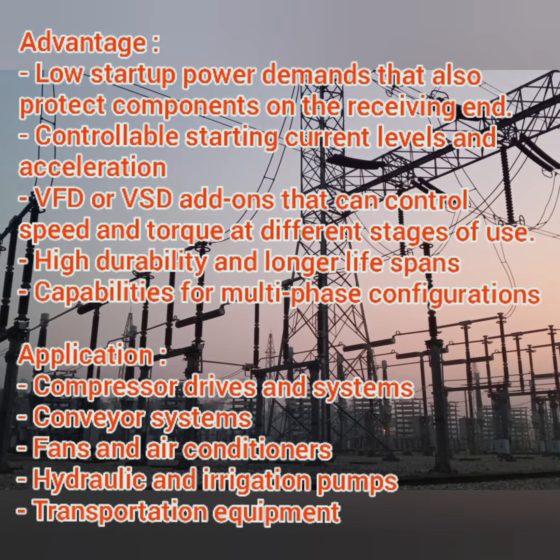Next, coming to the advantages, the main advantage is low startup power demand, which also protects the components on the receiving end. Second is controllable starting current level and acceleration. Next, VFD, variable frequency drive, and additional controls can be carried out in AC motors, which control the speed and the torque at different stages of use.